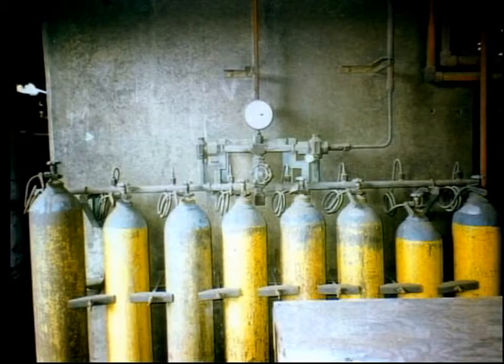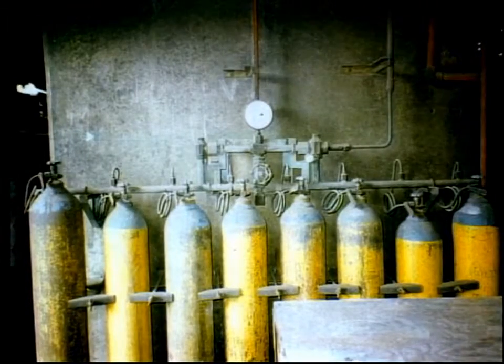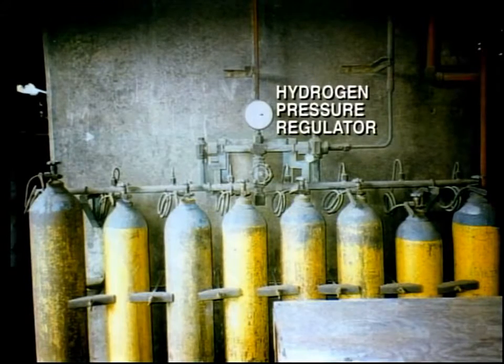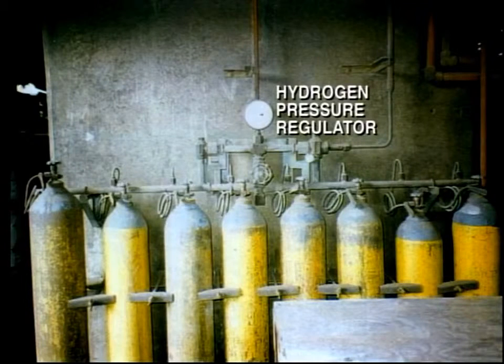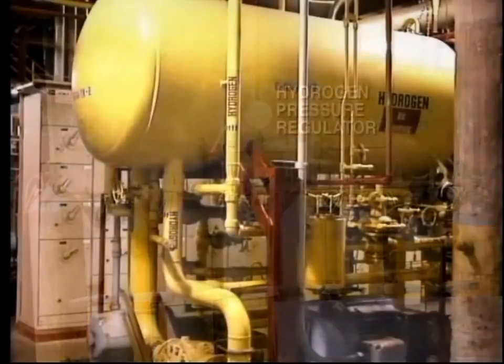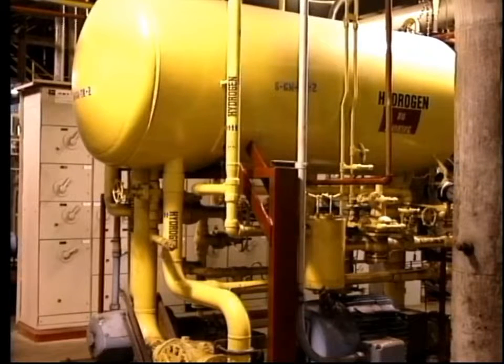Generally speaking, the loss of hydrogen is very small, but this still needs to be compensated. Makeup hydrogen is added through an automatic pressure regulator, which is set to maintain the desired internal hydrogen pressure. The hydrogen manifold may be fed from hydrogen bottles or perhaps from a hydrogen tank installed in the plant.